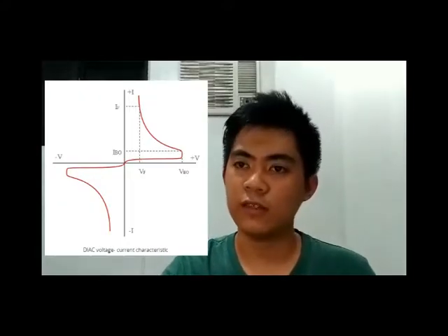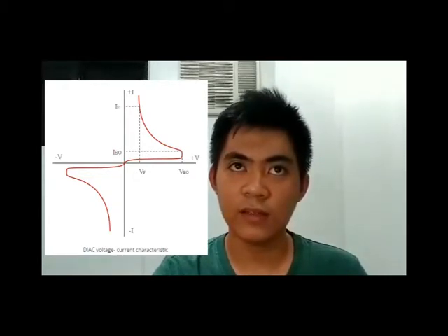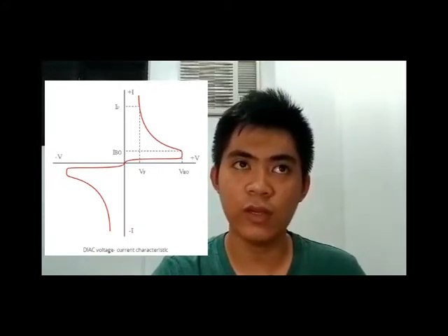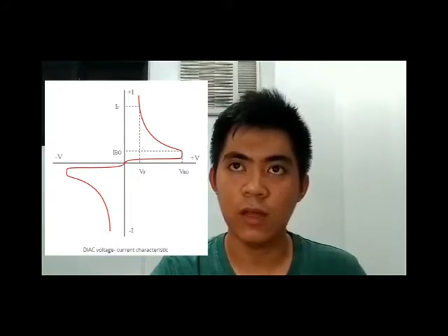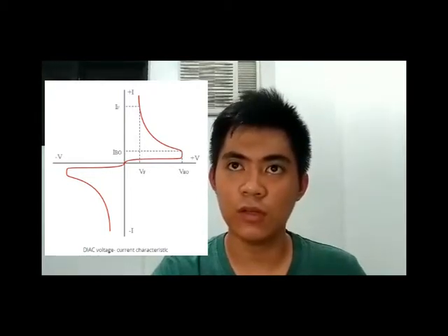Here is the characteristic curve for the Diac. Diac circuits use the fact that Diacs only conduct current after a certain breakdown voltage has been exceeded. When the Diac breakdown voltage occurs, the resistance of the component decreases abruptly, and this leads to a sharp decrease in the voltage drop across the Diac, and a corresponding increase in current.